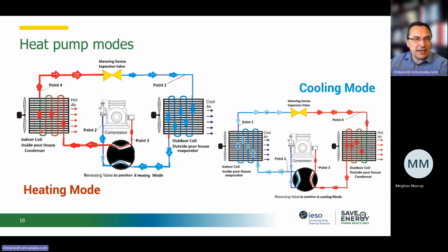Obviously, the heat pump in the winter mode will operate harder. If you think about the temperature difference between the outside and the inside air, because that's what the refrigerant does. It basically transfers heat from the outside air coil to the indoor coil. The temperature difference is much higher during the winter. Therefore, the heat pump is going to work much harder during the winter, and we see that efficiency being impacted in heating mode.